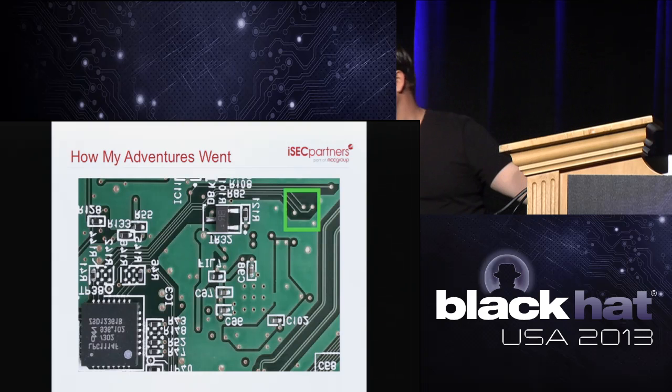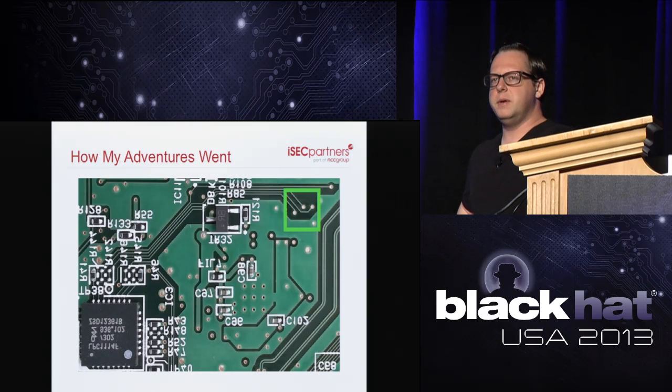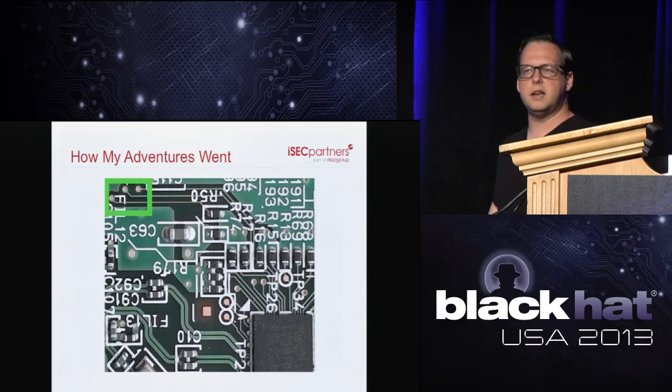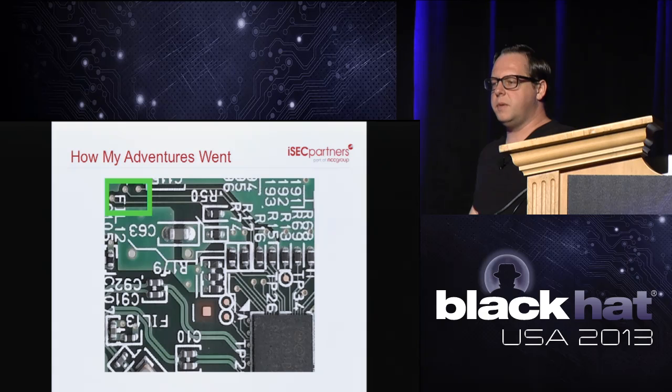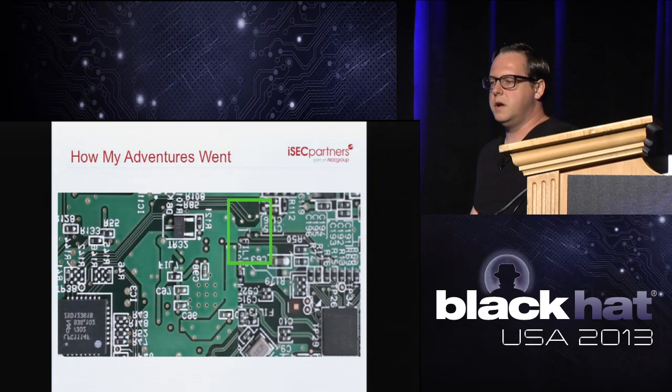Just by visual inspection, I'm able to check out the lines coming out, and they kind of drop into vias in this pattern. If we continue looking on, flipping the board to the other side, we can see those same vias popping up, coming into Thunderbolt. So with our little image editing magic, maybe hard to see in this image, we can kind of flop those two together and establish a direct connection.